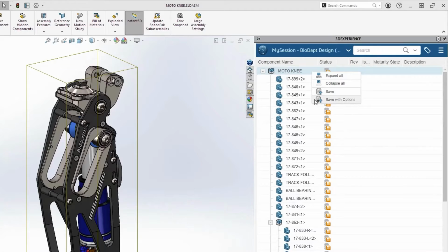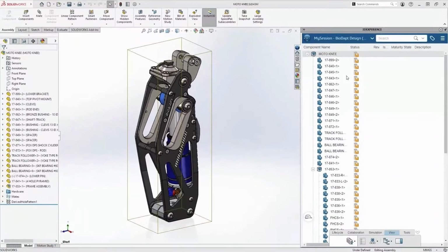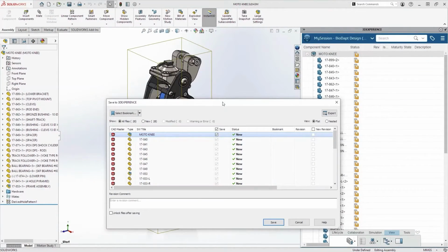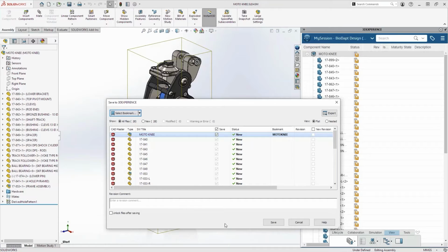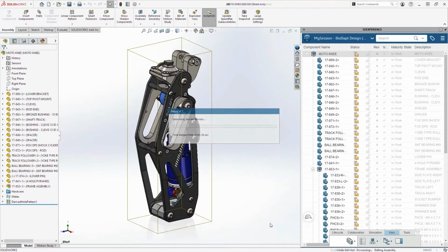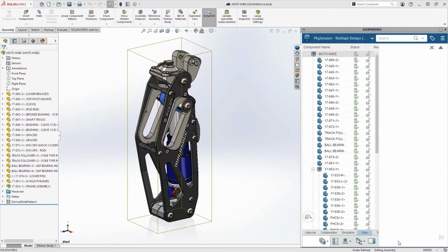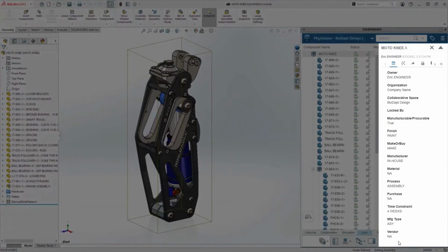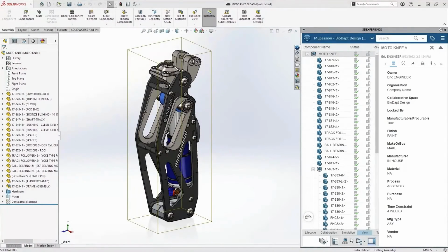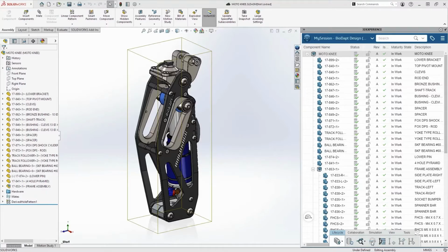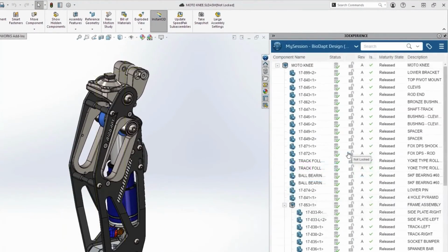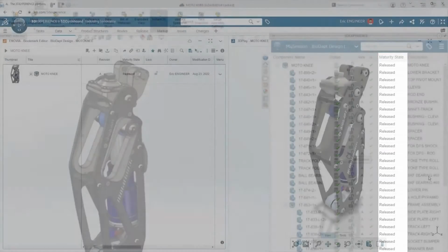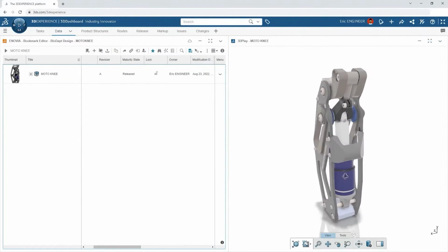With the 3DEXPERIENCE platform, there's minimal configuration, so within minutes, Eric is able to begin securely saving his data to the cloud directly from SolidWorks. Bookmarks provide a familiar way for him to organize and structure his designs, so with a simple click to save, Eric's design is secure. His custom properties are extracted, and with built-in lifecycle management, he can control design access privileges simply by updating the status. Without purchasing a single server, Eric's team can now access his designs from anywhere with a web browser.